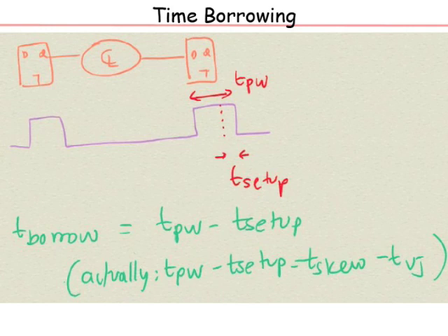It also turns out, I have not discussed here, but you can also hide some of the clock skew for the same reason. For example, if this clock comes a little earlier, this edge comes a little earlier, it is okay, because there is a transparent phase out here. The data comes and it will still make it through. So it has some skew tolerance. So my clock, I am able to tolerate skew up to TPW minus T setup.